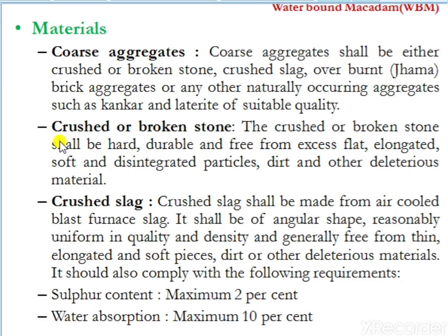It should possess sufficient strength to take up the vehicular load, and the material should be durable. That means the lifespan of the material should be long, and the material used in the construction should be free from excess flat and elongated materials.